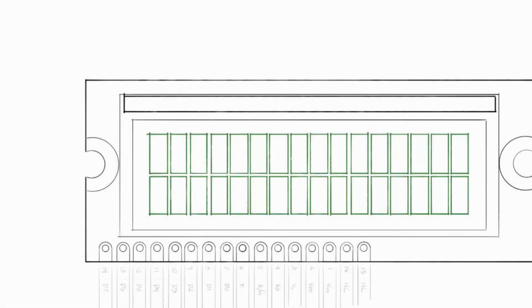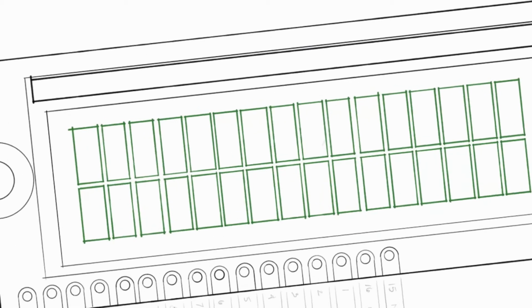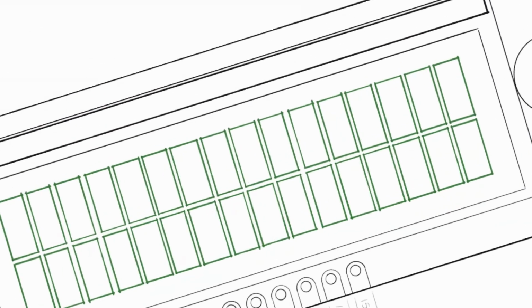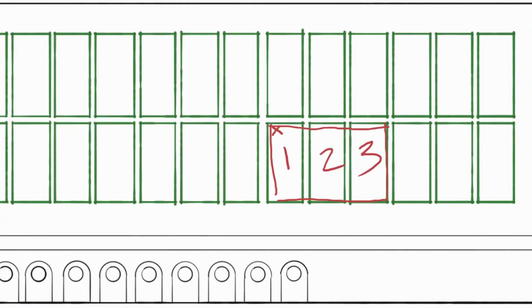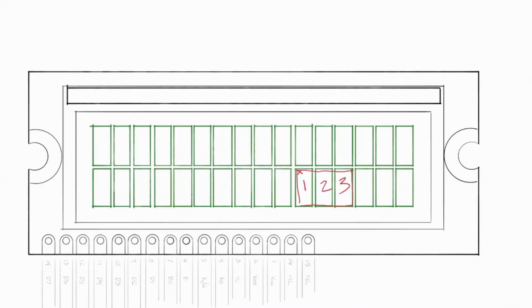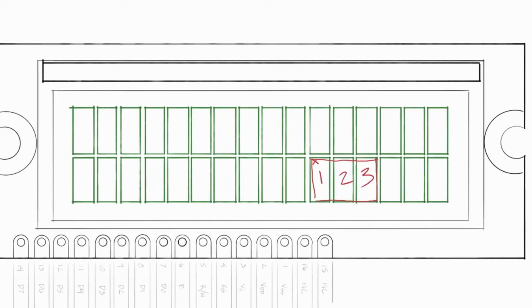The only function that we're really missing to add to the LCD functions is to insert characters at any location on the LCD. Let's say we want to have a number placed in these 3 digits, and we always want those digits to be in these 3 locations. So you'll need to know what location that particular digit is. The alternative would be to always clear the display and start from this location and then start writing whatever we need on this line, and then going to this line and writing whatever we need to go on this line. And in the case of just putting a number in this location, we would have to first clear the display, go to the next line, and then have this many spaces to this point, and then write the number.